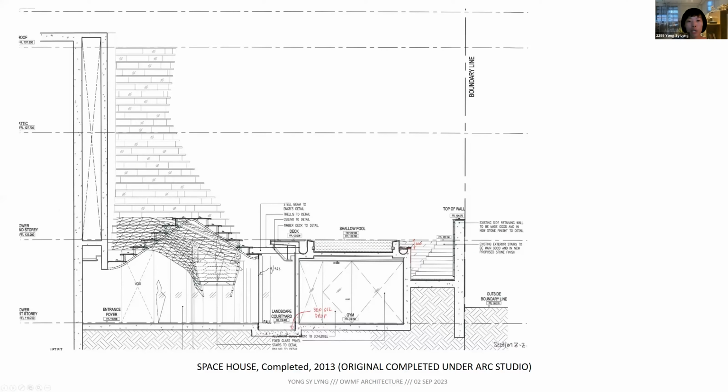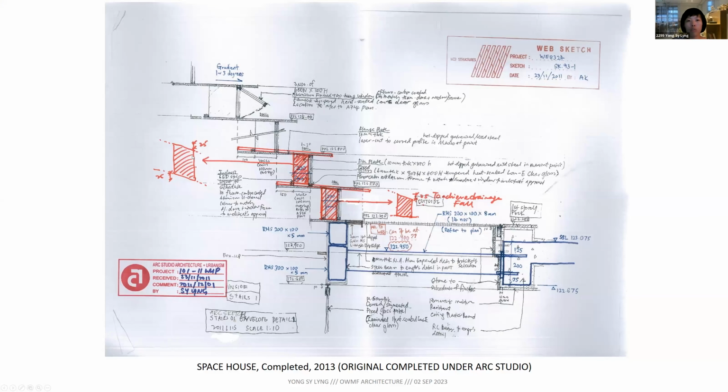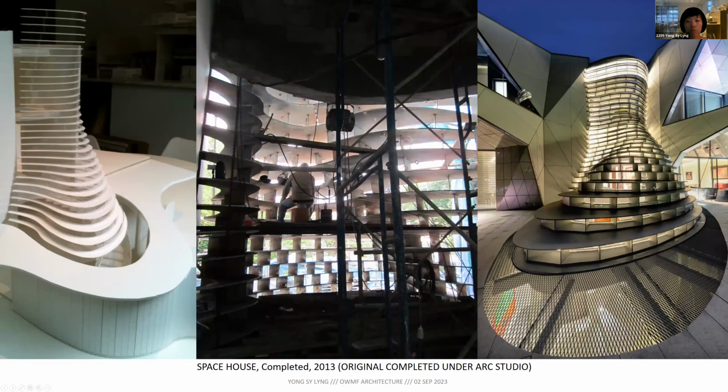So then I proposed vertical plates, right? These small, scattered vertical plates all over the fins, like this, as you can see. So instead of one very thick one, we are now down to 20 mm, scattered and staggered all over the fins.